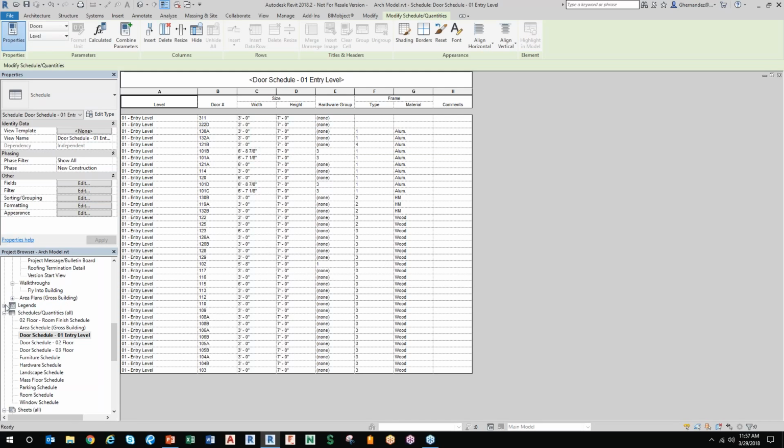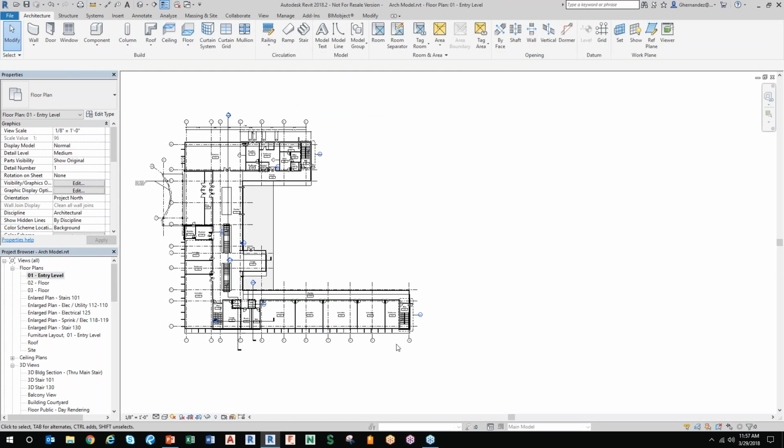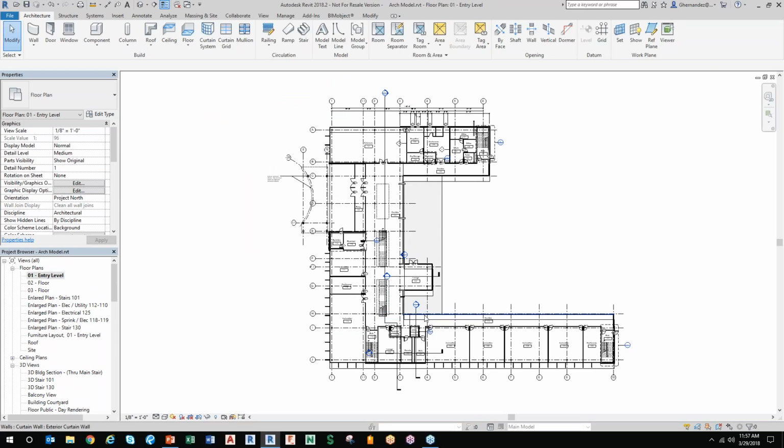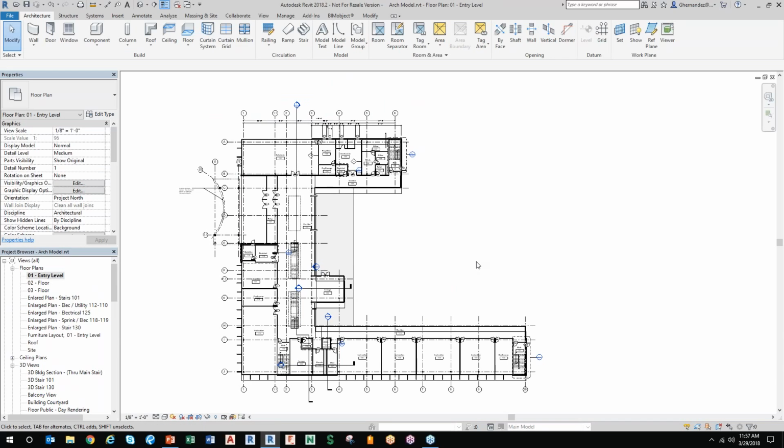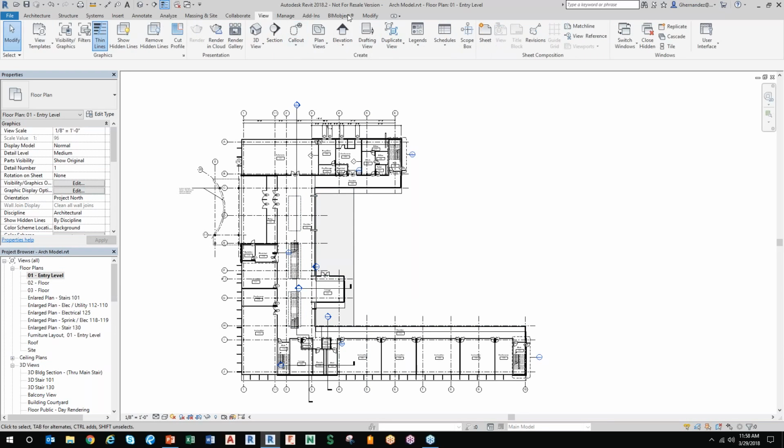Now, being able to go out to Excel and back in is really not possible natively. You'd have to have third-party apps or use a program called Dynamo. But these links are all here. Everything that you typically use in a CAD-based workflow, because you use OLEs or you copy-paste tables into AutoCAD, is a little bit different in Revit. You don't just use tables that way in a floor plan. You create them in the sheet and you create what we call schedules, which are views.